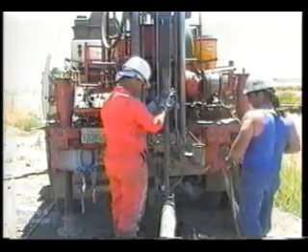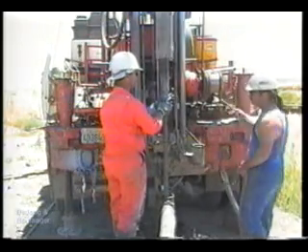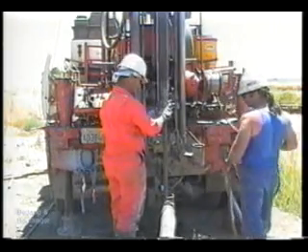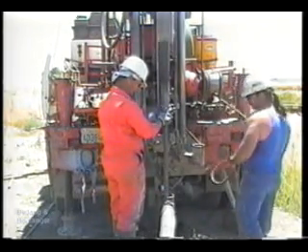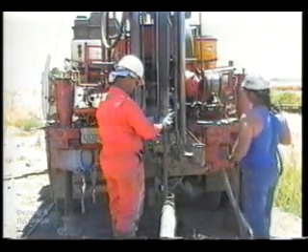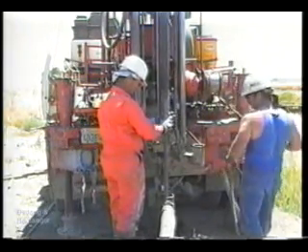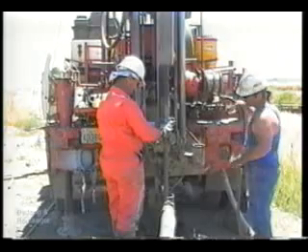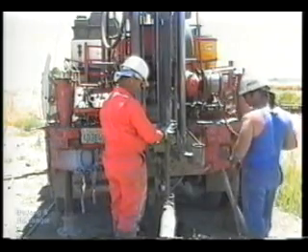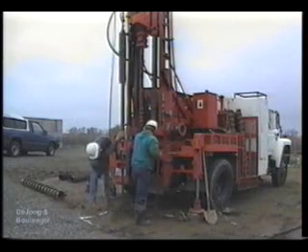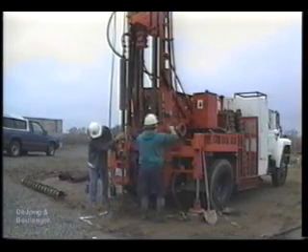The amount of energy delivered can range from 30% to 95% of the theoretical maximum. Since the N values are inversely proportional to the energy delivered, energy ratios of 30% to 95% can cause N values to vary by a factor of 3 or more. Mechanical trip hammers provide a more repeatable energy input, while the energy from drop hammers can vary as the driller becomes physically tired and slowly reduces the hammer drop height, number of blows per minute, and other variables. Thus, it is highly recommended that the energy delivered by a particular drill rig be calibrated on important projects.